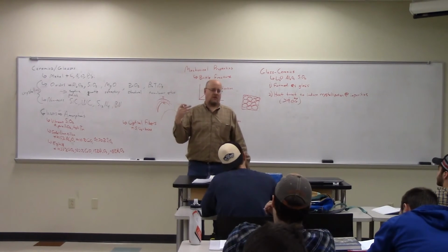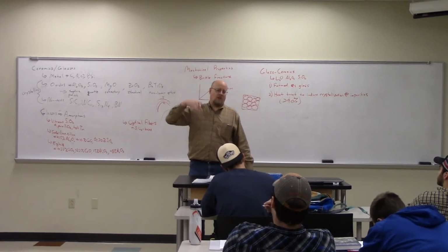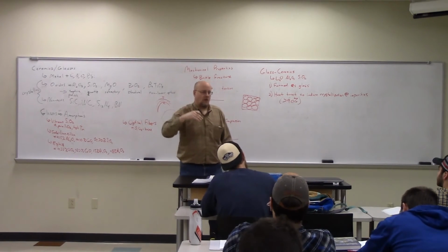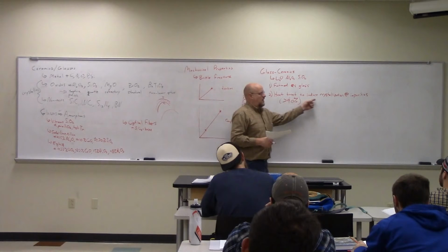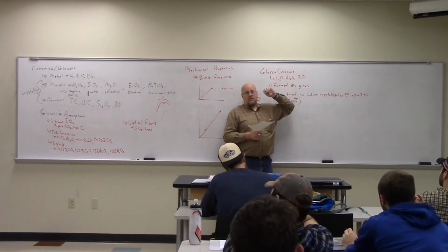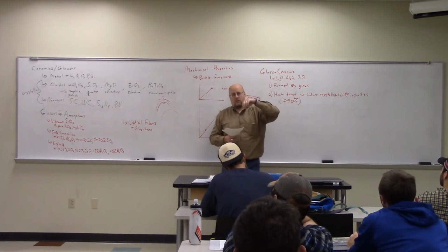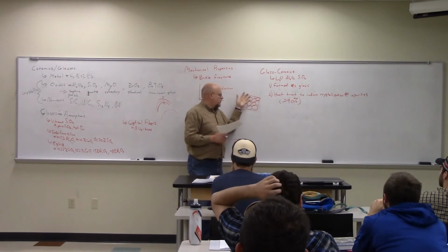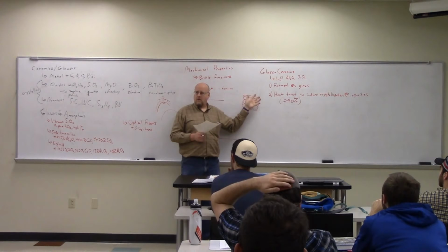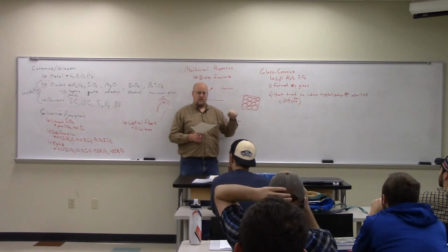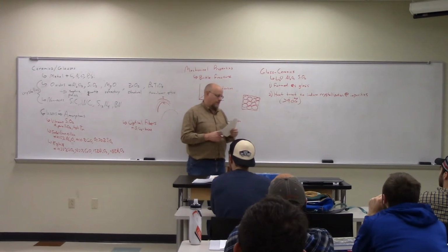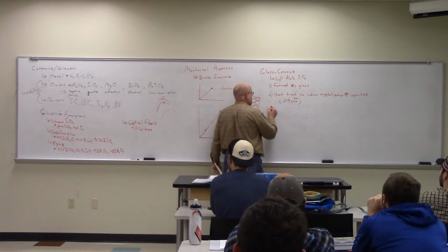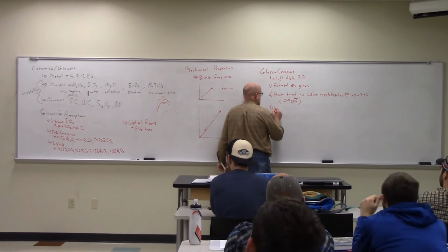If you don't have the titanium in there, then it's going to stay as a glass. It's going to be hard to get it to start crystallization. But because you put these little bits of titanium in the mix, those are sites where there's a disruption in the lattice, and it will begin crystallizing there, and then form the structure of crystals separated by boundaries of glass at the interface, at the grain boundary. This stuff is fine grained.